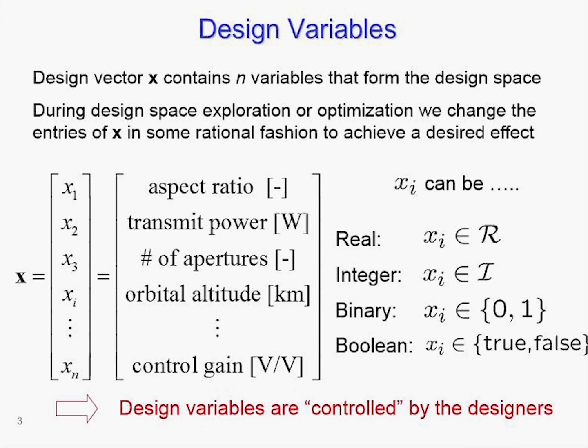And these weights would represent both some kind of a normalizing factor, because range is going to be measured in meters and is going to be on the order of thousands, whereas speed would be measured maybe in meters per second. It might be on the order of hundreds. Cost could be in dollars. So all these things have different units and different scales, but you could also use these weights to talk about your designer preference. I care more about cost than I do about noise, or I care more about fuel burn than I do about noise, and you could use the weights in that way. Okay, so if we have multiple objectives, either we have to roll them up into a scalar objective and think about what these weights would be, or there are some methods to do what's called multi-objective optimization.